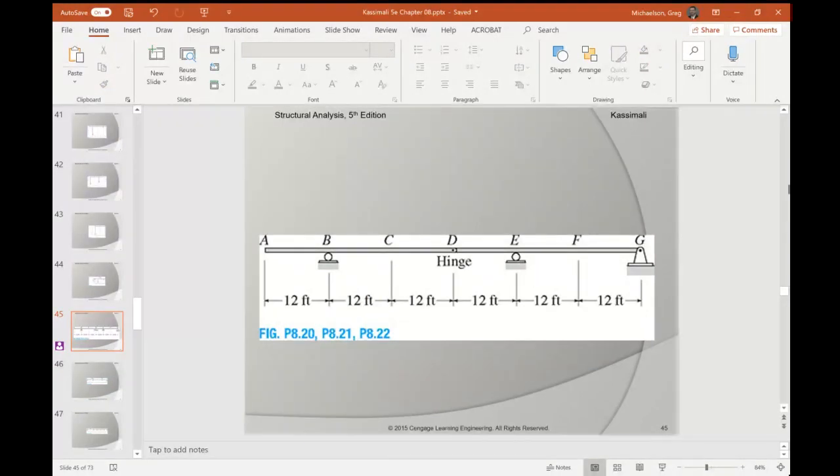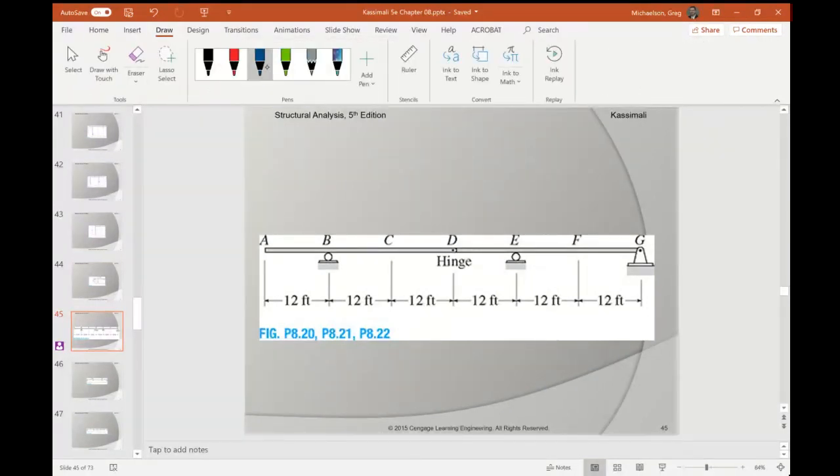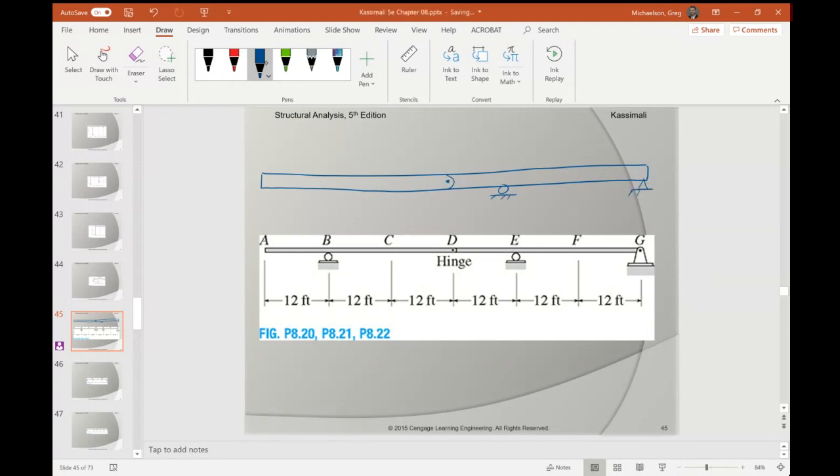Okay, so you're asking why it was 0 at the hinge? Here's why. Let's say you're drawing the influence line for the reaction at B. You remove from the structure the ability to resist the reaction at B. This is what the structure looks like when it cannot resist a reaction at B. Would you agree that that diagram is what the image looks like if it cannot resist the reaction at B? I've got the support at E, the support at G, and the roller at B, but I also have that internal hinge at D. Make sense?